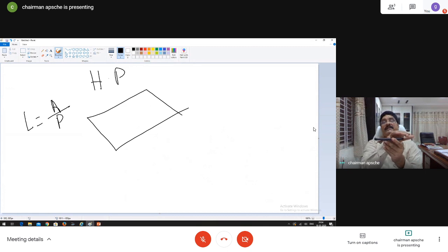Now, when this is a horizontal plate, I have two scenarios. One, the plate is hot. The plate is at a higher temperature as compared to the fluid. Now, the fluid molecules come in contact with the plate and acquire the heat. Now, they are not rubbing against anything. Straight away, it can move vertically because of buoyancy, there is no rubbing. Straight away, it gets detached, it moves up. Buoyancy force is upward because the plate is hot.